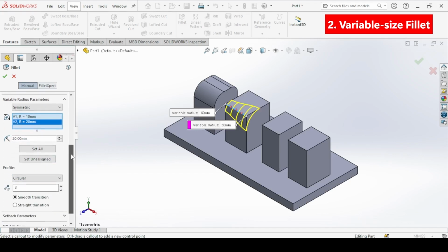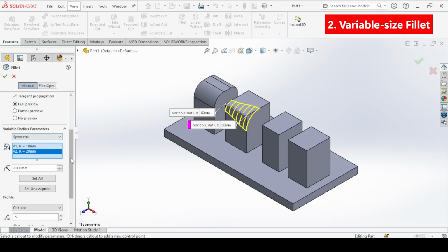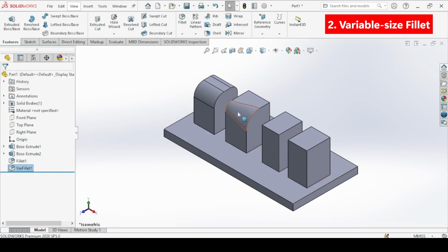Now we can have a smooth transition or a straight transition, as we can see here. So we'll go with the smooth transition. Now the number of instances, which will be the number of points inside the fillet, will determine how smooth the fillet is. You can set it to, let's say, 5. And you can see the transition here. So okay, and this is the variable size fillet.